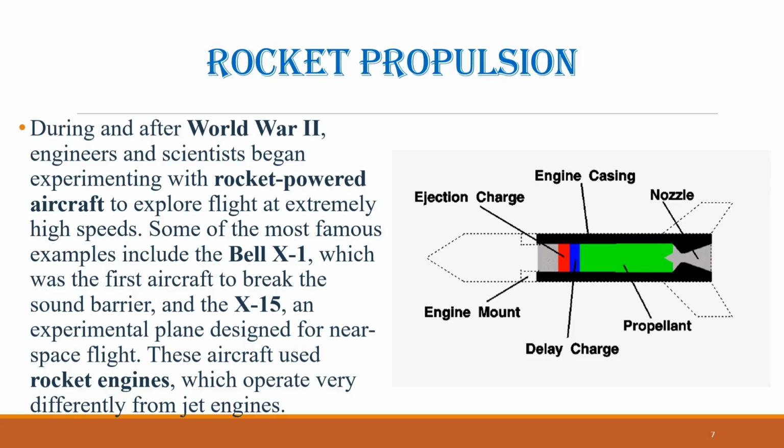Once ignition occurs, the combustion continues until all the propellant is consumed, meaning that the thrust cannot be turned off or controlled mid-flight. To stop a solid rocket's operation, the only option would be to destroy the casing, which is obviously not practical. Although solid rockets lack controllability, they are simpler, lighter, easier to handle, and can remain ready for use for years without maintenance, which makes them ideal for missiles and booster stages in space missions.